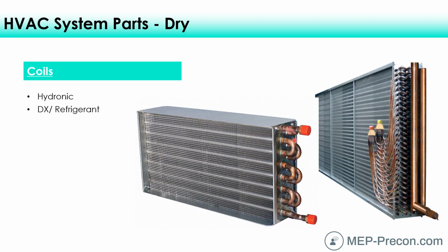And so these tubes are pretty big, just like the tubes on the radiator of your car. And then air flows by there and it exchanges heat through the fins that are solidly attached to these tubes. So there's heat transfer that takes place. The heat is transferred from inside of these tubes.